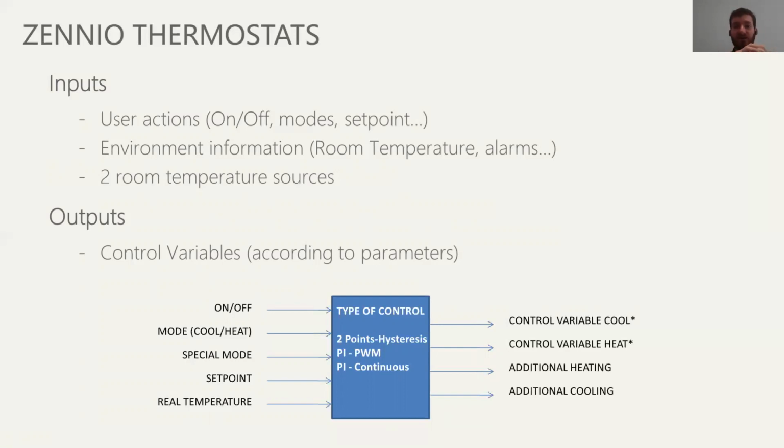In case you find that useful, it's actually very, very useful if you want to check the actual response from the thermostat. So you have the 1 bit object opening and closing the valve, and then you have, in a display or a user interface, the 1 byte object telling you, now I'm on 70%. So you know the valve is going to be open for 70% of the time.